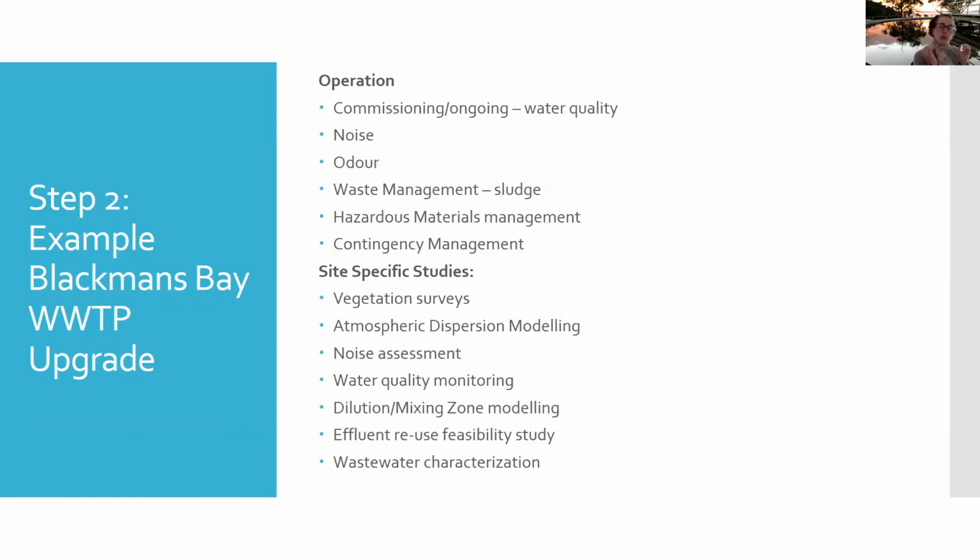And the waste that will come out of that will be different to that when it's operating. Because if you can imagine, not all the stages will be operating, and therefore you might have a higher level of waste or contaminants in commissioning than you might in operation when all the equipment is functioning and supporting the treatment of that waste. In operation, you'll have noise, you'll have odour, you'll have sludge, which is the solids from the wastewater treatment plant that sinks to the bottom of these tanks that I'm sitting in, and that needs to be removed and disposed of. You'll have chemicals. Chemicals are used in the process of treating wastewater.